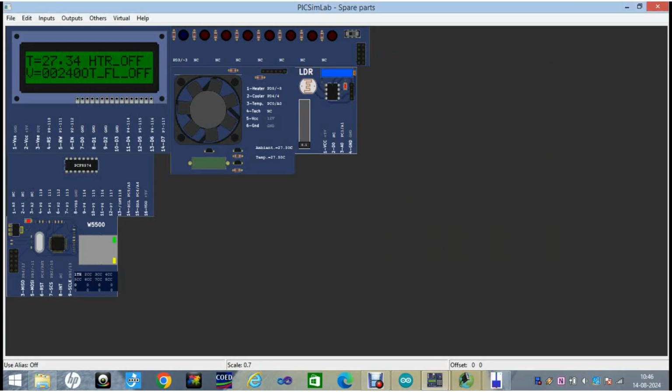Now we are remaining with the main module, which you can consider as the heart of the system. This is our Ethernet module, which will be communicating with us through the Blynk application or through the Blynk cloud. Since Arduino is not capable of internet connectivity, we have to use the Ethernet module, or we can use ESP32, but we are not using ESP32 here. We are using the Ethernet module here. The Ethernet module will help us communicate with our system. This is the main fundamental thing of the system. This is what we are working for.